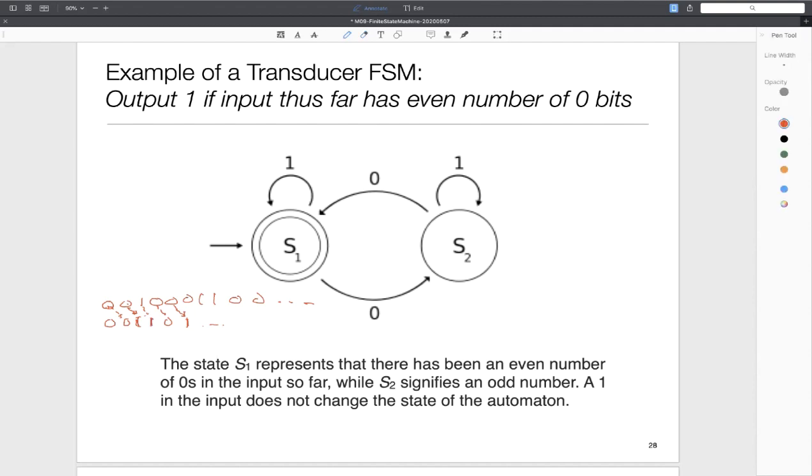Thank you. The other thing I would point out is I'm drawing the output delayed by a clock. That really depends upon whether I'm thinking of the machine as a Moore machine or a Mealy machine. In the case of a Mealy machine, the output would come immediately as soon as the input comes, whereas in Moore, it's typically delayed. That's not really material as long as we realize that the output is caused by a corresponding input. Depending upon the type of hardware, it may appear in the same clock tick or the next clock tick. So that's really a function of that.